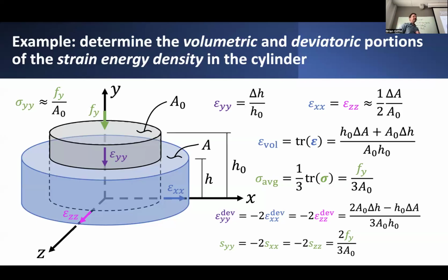And really, it's strain energy density. It's the amount of work I have to do per unit of volume of some small chunk of material. And we define strain energy as the sum of all of the incremental work that we have to do as we continue to stretch the material from an undeformed state into a fully deformed state.